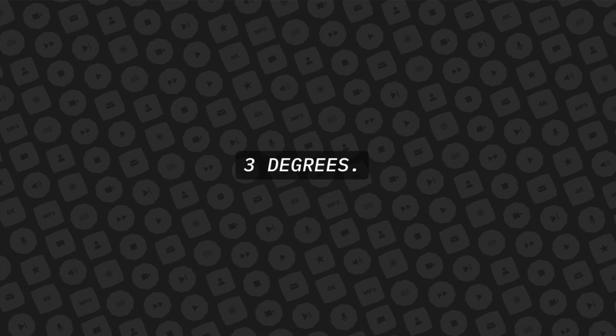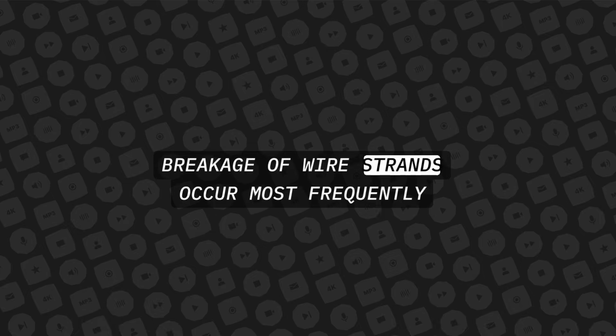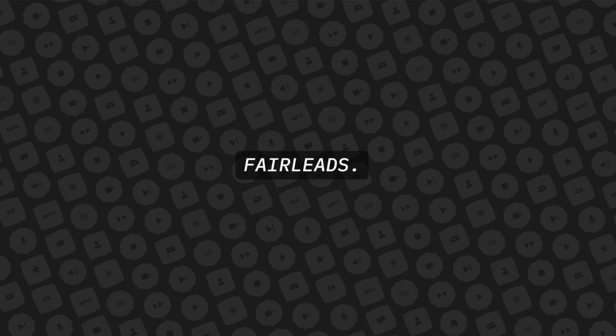3 degrees. Where does failure of control cables occur most frequently? Breakage of wire strands occur most frequently where cables pass over pulleys and through fair leads.